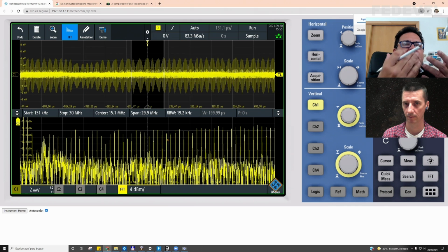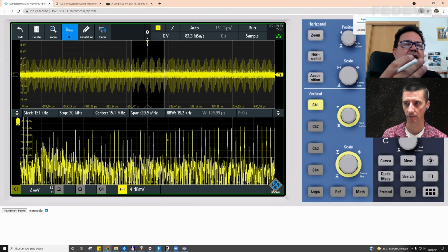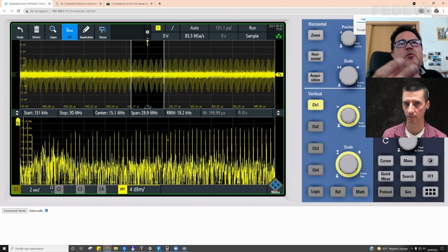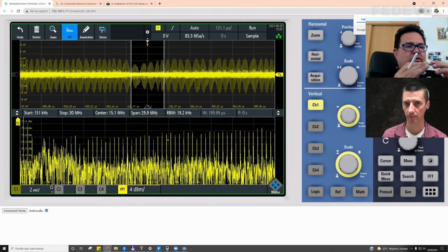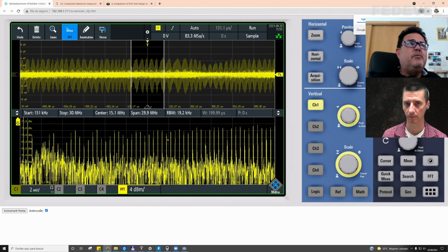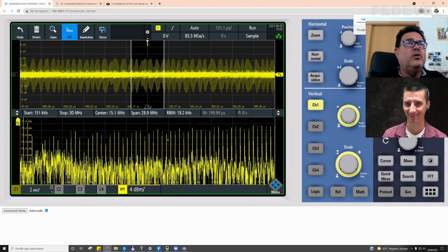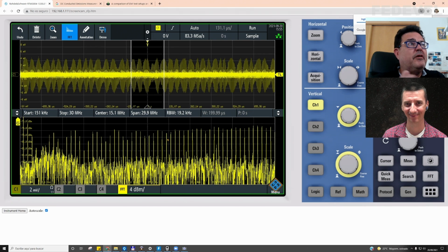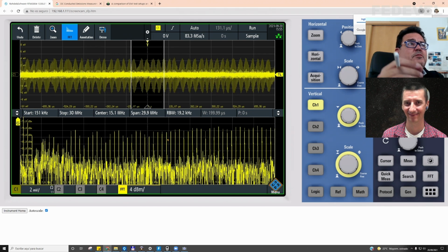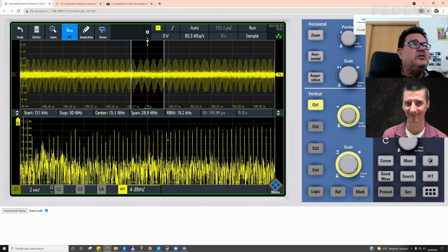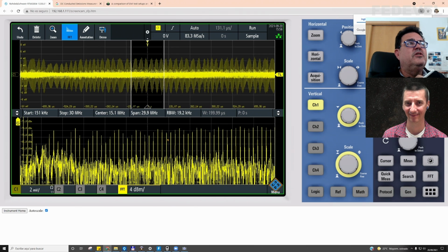So in many situations in electronic products, especially in companies where there is no EMC department or EMI people, what many designers do is take the filter that was working in the previous model and try to introduce this filter in the new product. If the system is working, perfect. If not, they try to tune by trial and error, introducing more capacitors, bigger capacitors, another common mode choke, until they arrive at the solution.